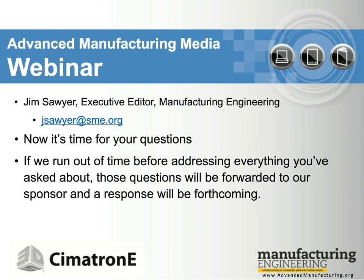So we have an electrode UCS and an NC UCS so that they don't have to be the same. The electrode UCS can go to the bottom of the puck and the NC UCS can go to the top of the trode, but it doesn't mean you have to pick up the top of the trode when you machine it. I can program to the top of the trode, and then post from the bottom of the puck. So I'm right there with you on not having to change all these things. The way that you're doing it is the right way.